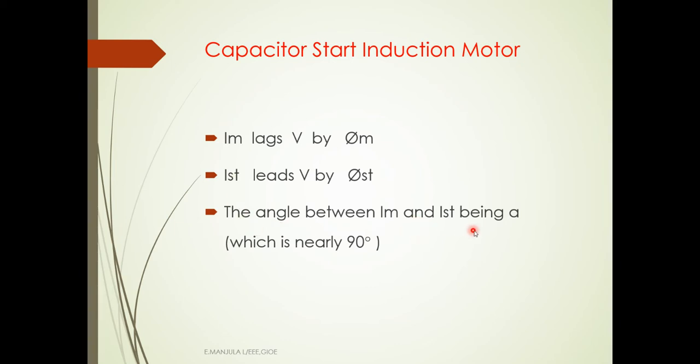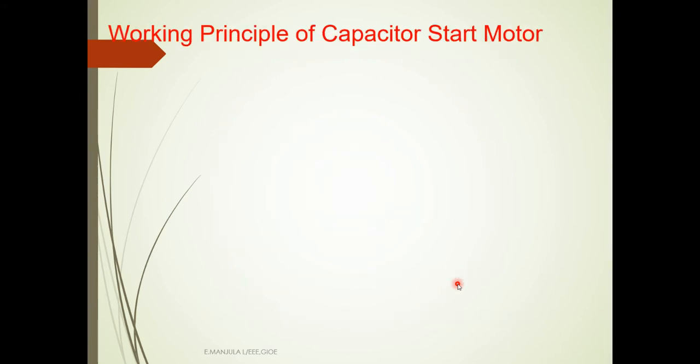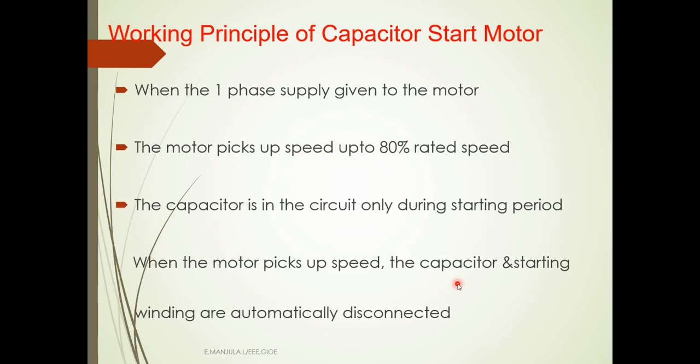So the angle between I_m and I_st is nearly 90 degrees. The phase displacement is achieved, so the motor develops high starting torque.